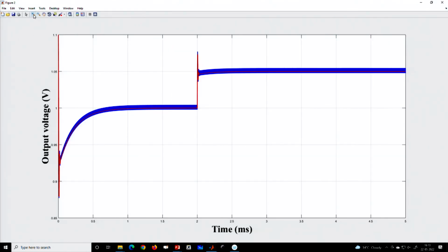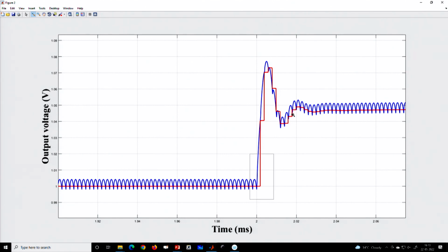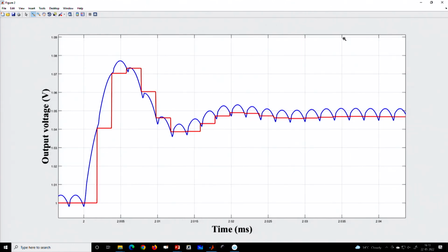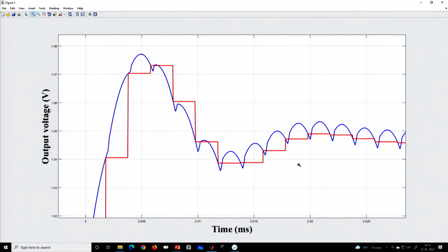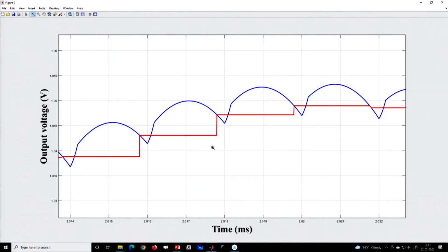I have not yet discussed the digital control design, that is why I have chosen some arbitrary value of the controller gain, just to show that you can realize this controller using MATLAB. And here we are incorporating delay. You can see the sampling time and the switching times are different. Sampling is happening fast and then switching happens. So, you can customize this delay.